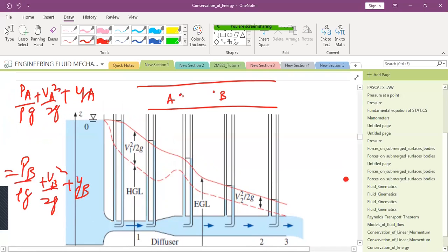लेकिन मान लीजिए ये तो मैंने आइडियल केस बोल दिया, एक्चुअल में ऐसे होगा? नहीं, क्यों नहीं होगा? क्योंकि फ्लूइड की विस्कोसिटी जैसा आप बता रहे थे वो इंटरफेयर कर जाएगी इनविसिड रीजन में, तो कुछ ना कुछ जो एनर्जी है वो डिसिपेट होगी, तो मुझे क्या करना चाहिए, पीए में से इस पूरे टर्म में से कुछ सब्ट्रैक्ट होगा ना. इसको मैं हेड लॉस लिख सकता हूं.